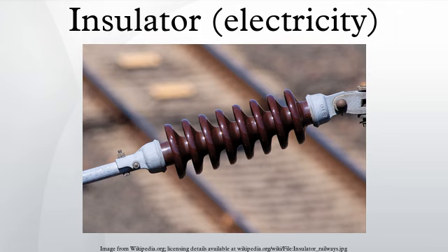These insulators are usually ceramic and cylindrical or egg-shaped. This construction has the advantage that the ceramic is under compression rather than tension, so it can withstand greater load, and that if the insulator breaks, the cable ends are still linked. These insulators also have to be equipped with overvoltage protection equipment.